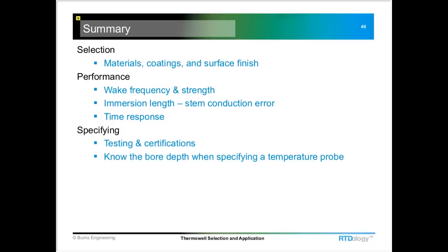And then when you're specifying a temperature probe for a Thermowell, whether it's a thermocouple, RTD, a bimetal dial thermometer type thing, or even an older liquid in glass thermometer, we need to know the bore depth of the Thermowell so that the correct length temperature probe can be selected for that particular well.